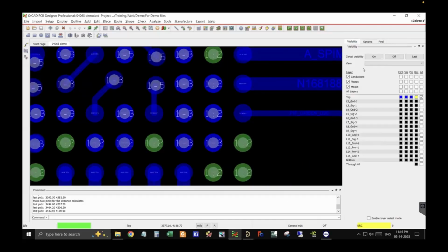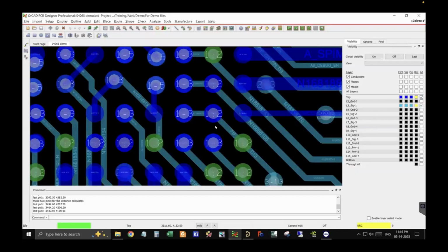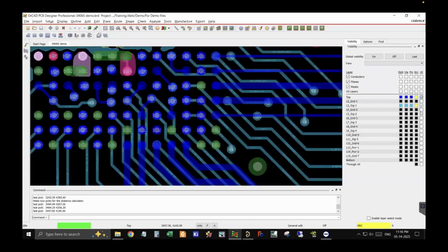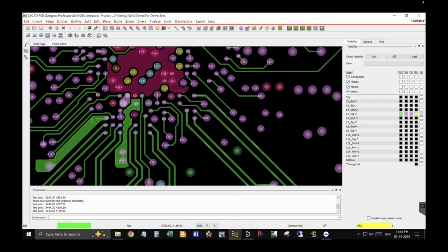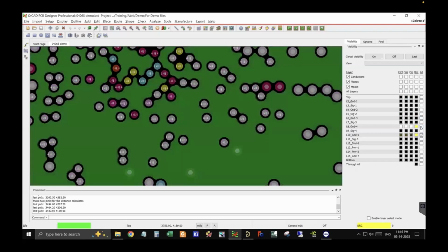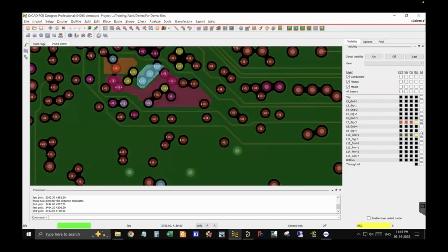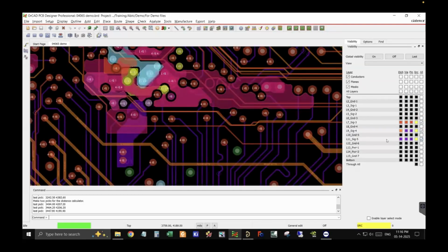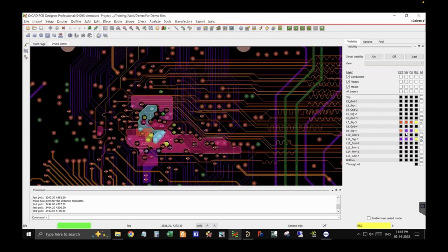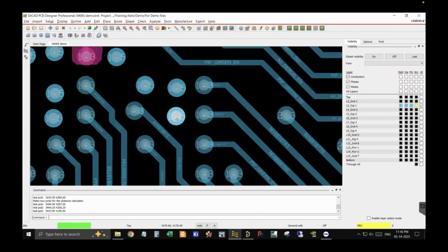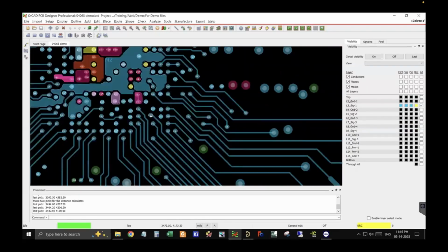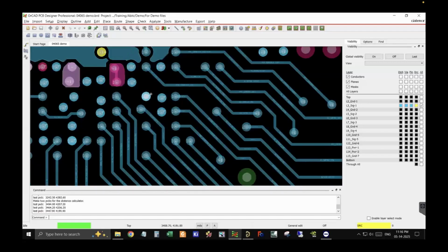So the next thing is we had used stacked wires, not staggered wires, and the reason is, as you can see, these traces on inner layers. So this is layer 3, this is layer 5, then layer 7, 9, no, sorry, this is layer 7, 9, and 11. So many traces. Now imagine if this is layer 3, as you can see, this is now stacked wires. Even with that, it looks like there is not enough space for placing more wires over here.